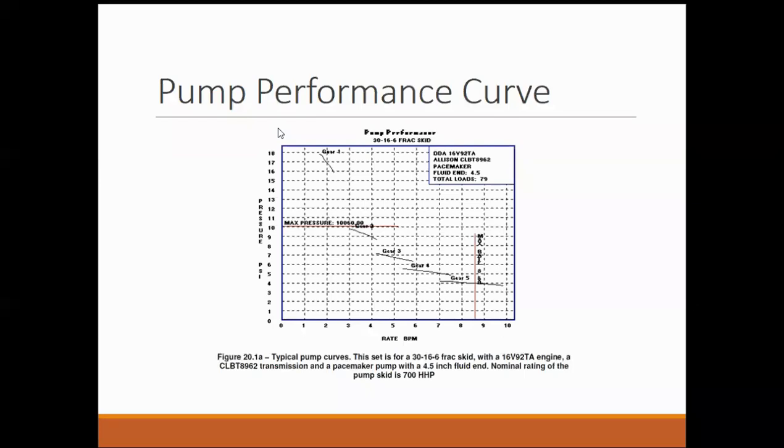Okay, so this graph shows at what rate, what is the maximum pressure that you can get, and at what gear. So the pump operator basically should be aware of the pump curve, because he's the one who's going to operate it. And as an engineer, you should be aware of the equipment's limitations and the kind of performance it is about to give during your frac job.